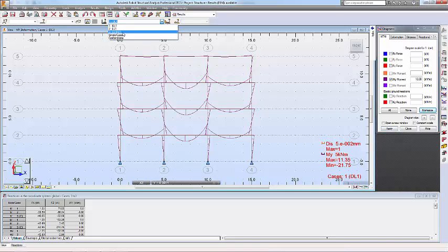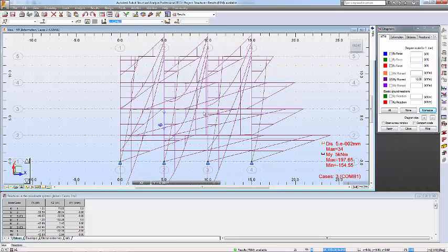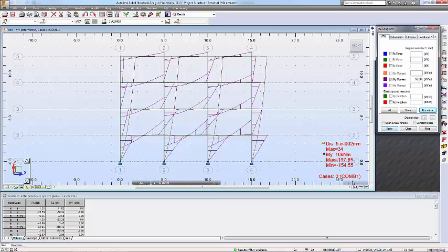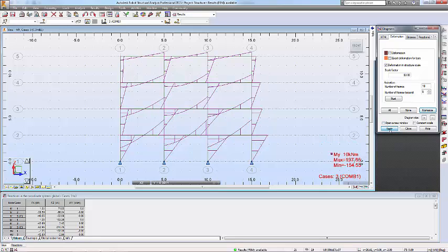And if you want to see the combined effect, that's the combined effect. Of course, the displacement form is involved in here as well. And then because the scale may be too big once both connect together, let's put in 50 here, just click apply. Again, we need the deformation, maybe we need to tick this one here, so apply. So then we can see this is the combined effect with the lateral loading and the vertical loading. So that's all for the first example. Let's have a look at the second one later.